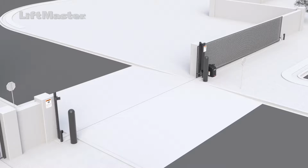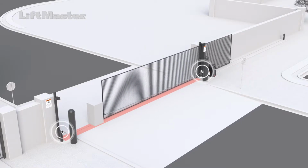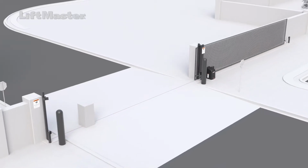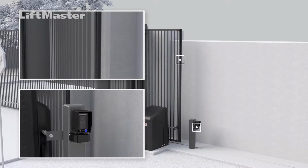The new UL guidelines became effective on August 1, 2018. For a slide gate operator to function, the operator requires a minimum of 2 external monitored entrapment protection devices, 1 in the open direction and 1 in the closed direction. Check for a minimum of 1 external monitored entrapment protection device to be installed in either direction where an entrapment zone exists. LiftMaster slide gate operators ship with 1 safety edge and 1 set of photo eyes to help you get started ensuring compliance with UL 325 guidelines.